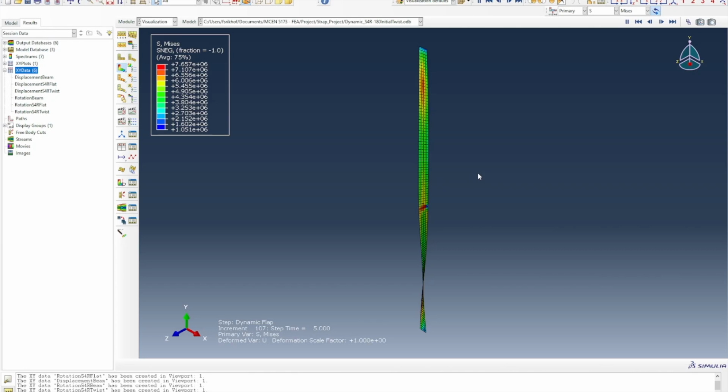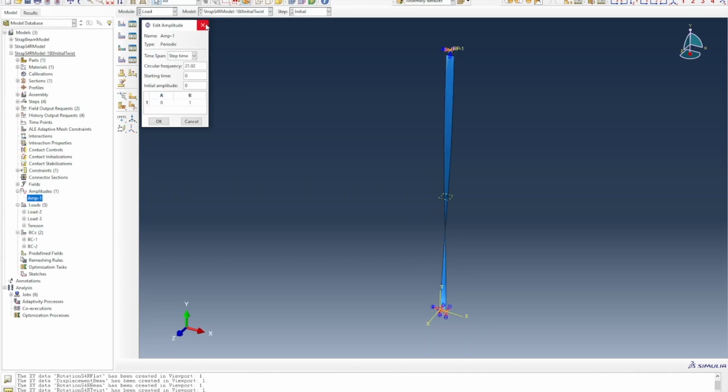So overall, this project was a lot of fun. When I started this, I was a little bit curious as to whether this would actually be possible without doing any sort of CFD to model the actual airflow. But I think, as you can see here, it is possible to approximate those aerodynamic loads using just moments and distributed forces.